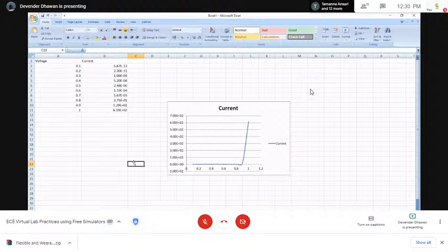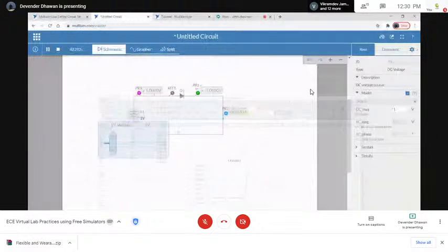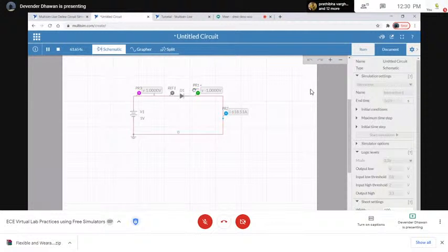So this was a forward bias we were checking. Similarly, we can check for the reverse bias also. This is how you can ask your students to plot the IV characteristics. So a simple circuit, a diode and a battery only. Then you put in your voltmeter and ammeter, and you can just try to work on it. So this is one thing. If you have any doubts, let me know. Otherwise, we'll move forward.